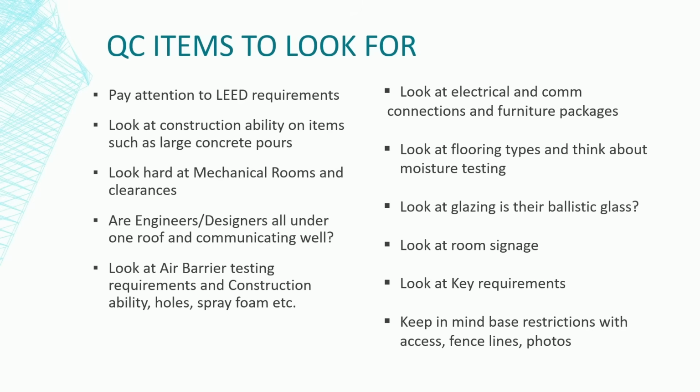Fence lines. If you are on a secured facility, a lot of times you're not going to be able to go within 25, 50 feet of a fence line. Pay attention to that, because designers won't. And they will try to set down utility lines right next to the fence, and that just can't happen. And access, right? So how is the access to the site? How is the access going to be for deliveries for concrete trucks? Think about all those things.